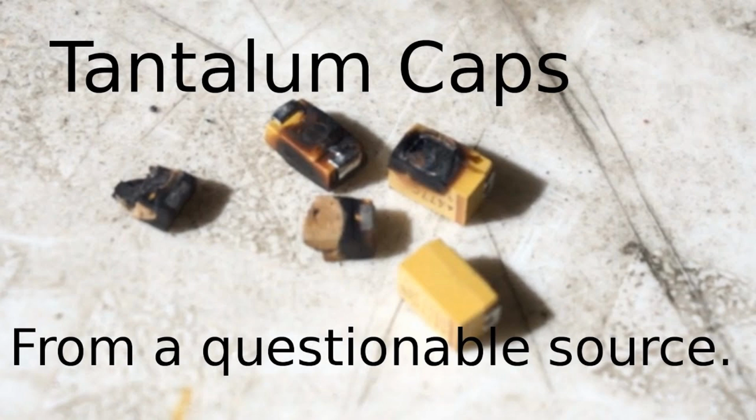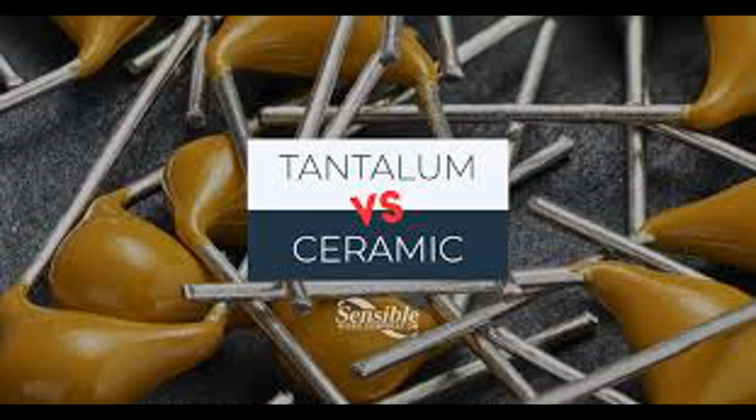1. High capacitance to volume ratio. Compact size. Tantalum capacitors provide high capacitance in a small package, making them ideal for space-constrained applications like mobile phones, laptops, and wearable devices. Efficient use of space. The porous structure of the tantalum anode increases the surface area, allowing for more charge storage in a smaller volume compared to other capacitors.